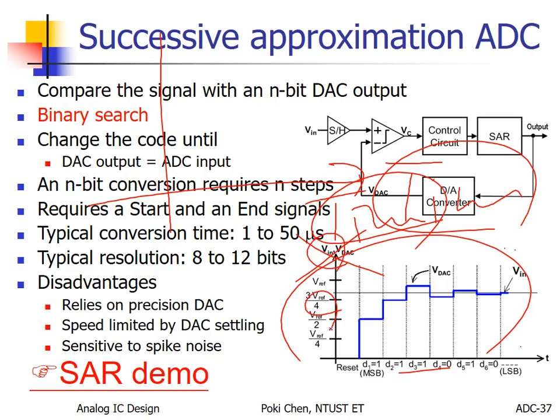Oh, piece of cake, right? So the idea is still the same. The input time is here. So for MSB, not enough. Second MSB, not enough. Third MSB, too much. Reset it. Blah blah blah. The same, right? So we don't create it. We didn't create the idea by ourselves. No, we simply duplicated the idea from voltage domain to time domain and realized it.